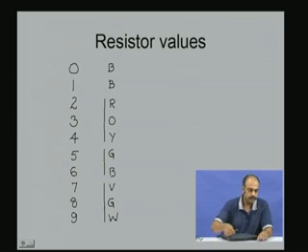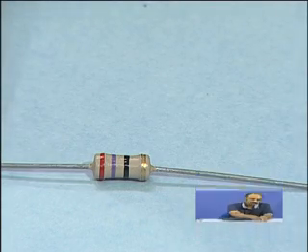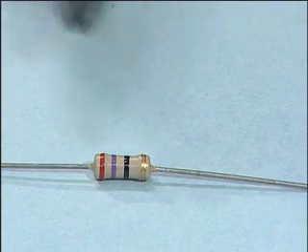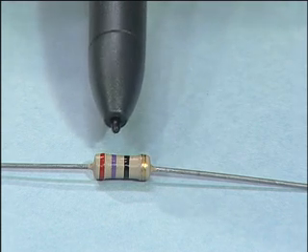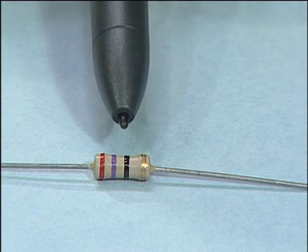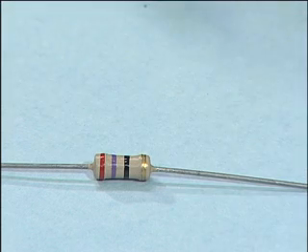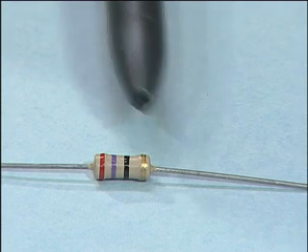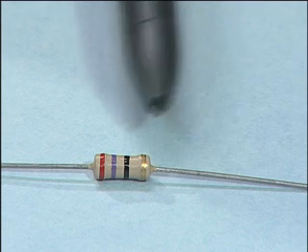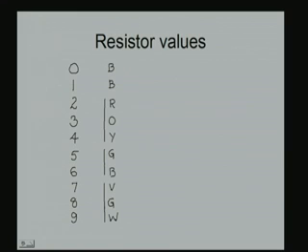What you see here is a resistor which has two leads. There is one lead here, there is another lead here, which gets connected to your circuit, and this portion is the resistive portion which impedes the flow of the current, and there is going to be loss, the I square R loss or the V square by R loss or V into I loss, any one of those equations. This is a carbon compound resistor, it is a half watt resistor. You see that there are some bands on the resistor here, red, violet, black, and so forth. The resistor value is recognized by the color bands that are drawn on the resistor.